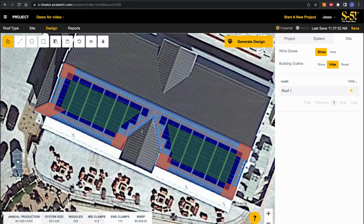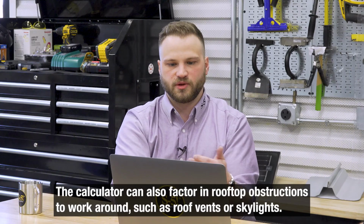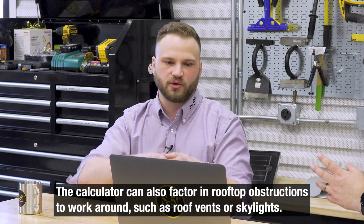So I'm going to deselect the roof again. There's other things you could do here as well. You could add in obstructions, maybe an obstruction on the roof. Maybe it's a roof vent that you don't want to put a module there. Maybe you want to even say, I want a 12-inch setback from this roof vent. There's capabilities of doing that. If you wanted to say, I have a tree here and I'm nervous about shadowing, you can draw that as well, and it'll illustrate the shadowing, so it'll remove modules from a portion of the roof, and you don't have to do any guesswork. So I don't think we want to dive into the weeds on that one right now, but just know it is there.